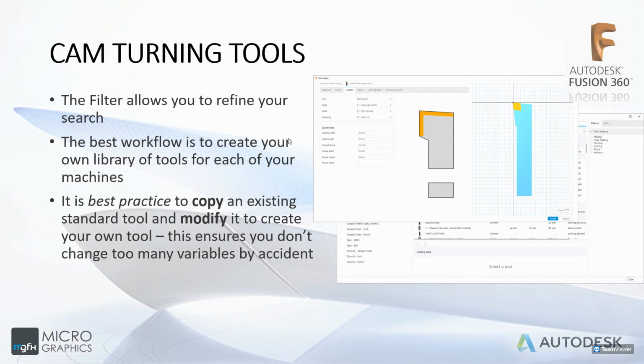Okay, again, I'm going to stress this one more time. Best practice is to copy an existing standard tool and simply modify the dimensions rather than to create it from scratch, because there might be some important data that you've missed or that you've entered incorrectly that will cause problems for you later on. And I will show you exactly how to do that when we get to the live demo.